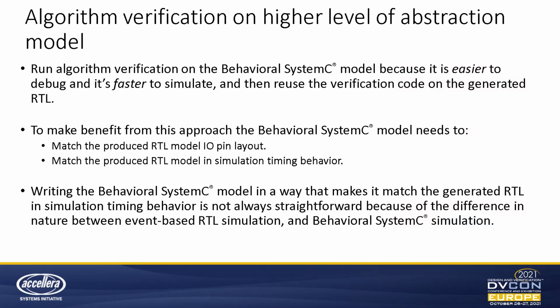When using HLS for design, the input implementation by the designer to the tool is a behavioral SystemC model. This model is at a higher level of abstraction and faster to simulate than RTL, and it's easier to debug as well. It can be used in a hybrid verification environment where we can switch the DUT instance between RTL and SystemC at compile time.